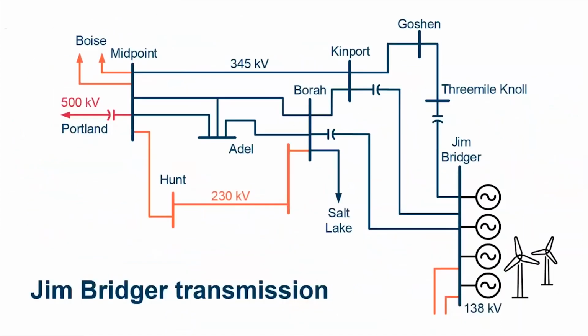Wyoming, with its abundant wind generation capability, has seen significant growth of wind farms in its eastern region. Some of the wind farms are being connected to the Jim Bridger Power Plant, and the power transmitted to the west of Jim Bridger now includes power produced from these wind farms. This sub-cycle remedial action scheme includes integration of these wind farm units as well as a part of this algorithm to preserve system stability while allowing system operators to push more power through their existing transmission infrastructure.